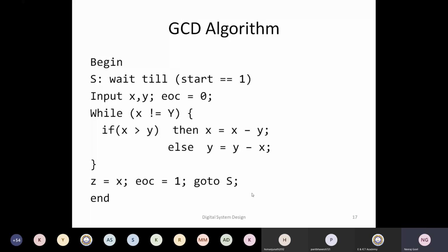So what are the resources required? What do we mean by resources here? Resources would essentially mean the number of registers, what function units, and what operations are performed. For example, addition, multiplication, in that case carry save adder. So what are the hardware function units that would help me in doing this task? Identifying resources, identifying how many resources, is the first step by looking at the application.